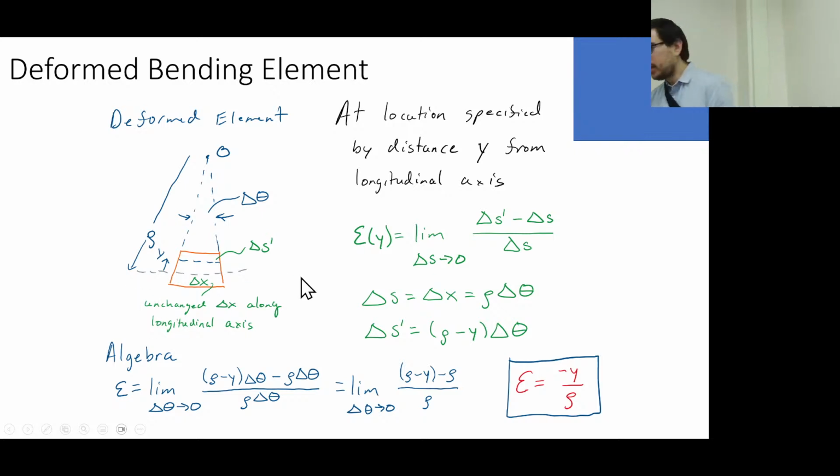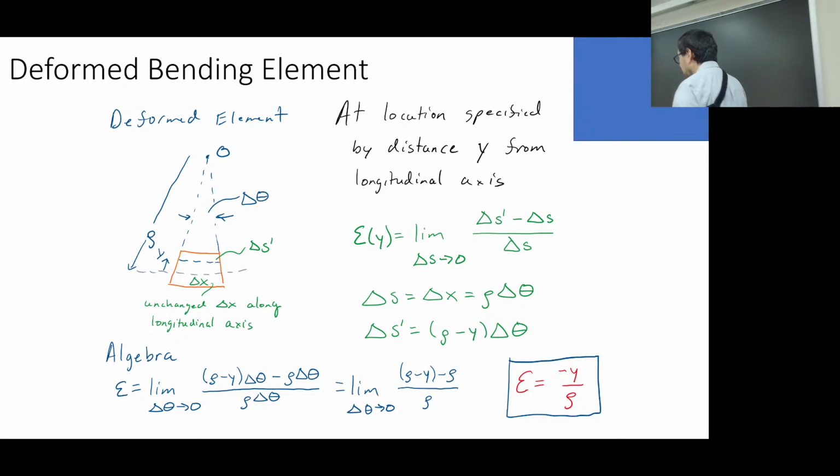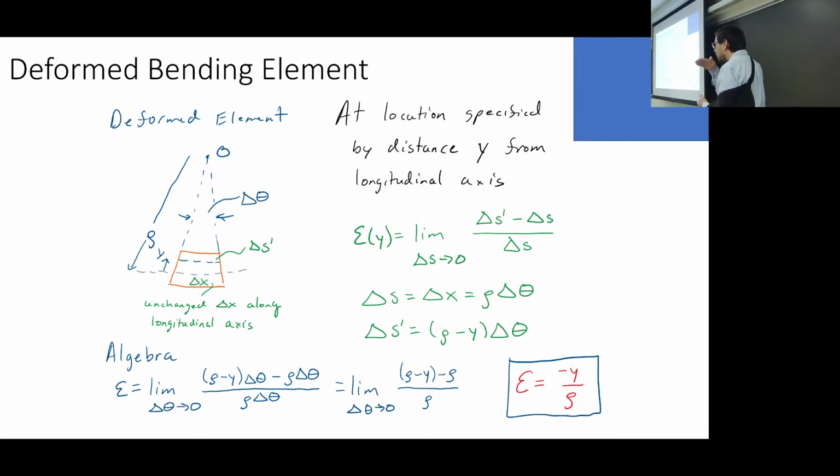So I think of neutral axis, you can think of longitudinal axis. It's essentially this line or this curve that I can trace along almost the middle, we'll say, okay? And there's ways to calculate this. Actually, it's kind of like the centroid of the cross section, okay? Is where you have this line of zero strain.